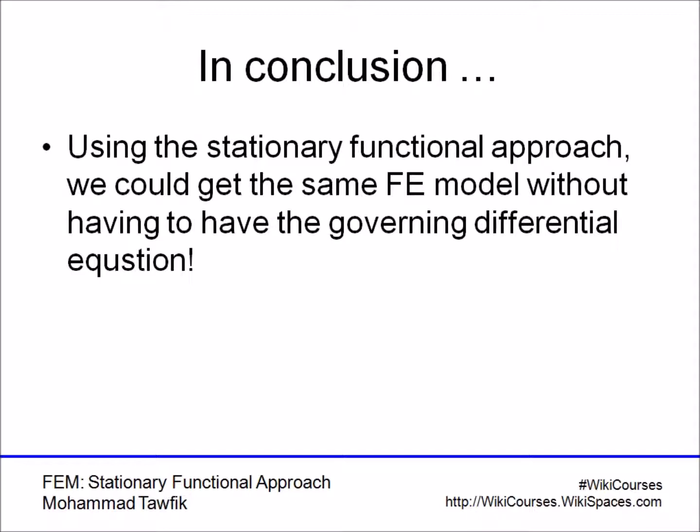We approach it from two different directions, but we get the same thing. If you have the differential equation, start with weighted residual methods. If you don't have the differential equation, or if modeling the differential equation is too difficult, start with the energy. You can always write an energy term, and you can always work with an energy term. You end up with the same finite element model.